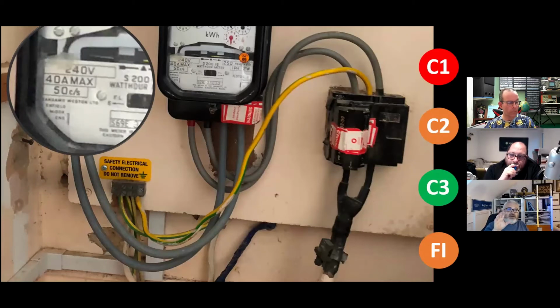Now, meters are supposed to be recertified between 5 and 15 years. Average is 10. If you look at the meter number itself, you can see just here, 69. So that was the year that meter was made, 1969. It's supposed to be recertified every 10 years, and the last time it was certified is on the orange sticker, which is 1989. That meter was supposed to be recertified in 1999, so it's 21 years out of calibration.